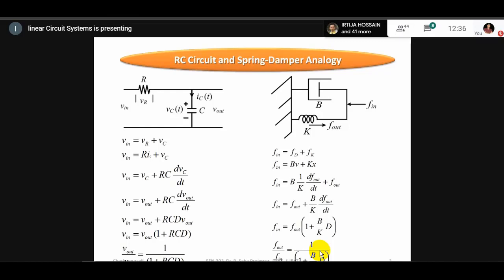And remember, transfer function is not the efficiency. Somebody may think, okay, V out by V in, it may be efficiency. No, not like that. Don't confuse the transfer function and efficiency, totally different. Efficiency has a relation with power, but the transfer function has no relation with power. It is voltage and current or its parameters.